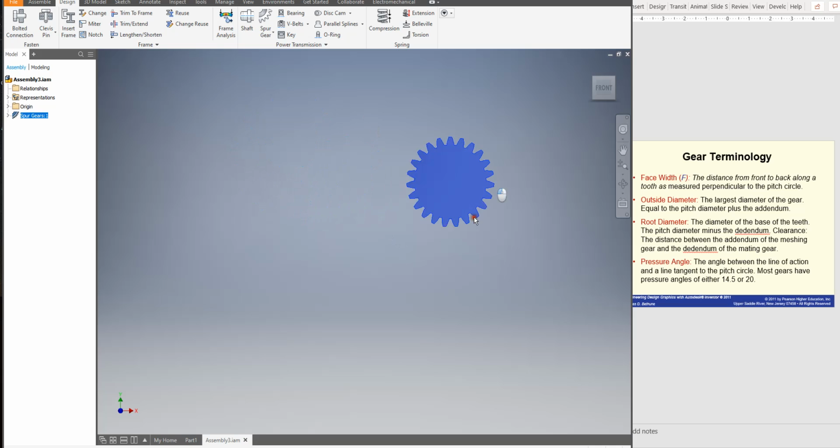What exactly I want this gear to do, it will be at the center of the file. And it should just rotate around the Z axis only. So I have to prevent movement in X and Y. I have to prevent rotation around X, around Y. And I should keep the rotation around Z axis. Okay? Now, how can I do that?